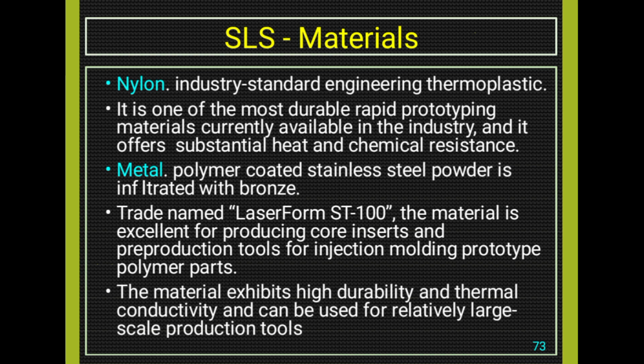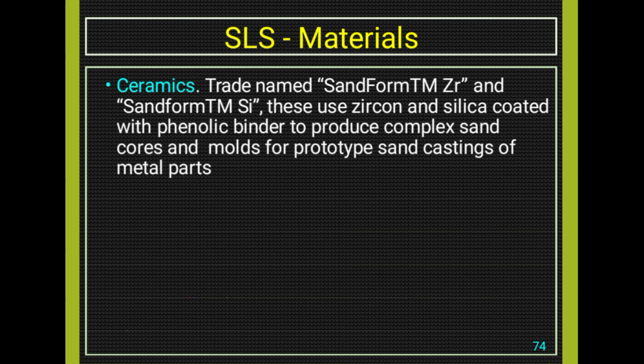The material is excellent for producing core inserts and pre-production tools for injection molding prototype polymer parts. The material exhibits high durability and thermal conductivity and can be used for relatively large scale production tools. This SLS process can be used for ceramic materials also to produce complex sand cores and molds for prototype sand castings of metal parts.